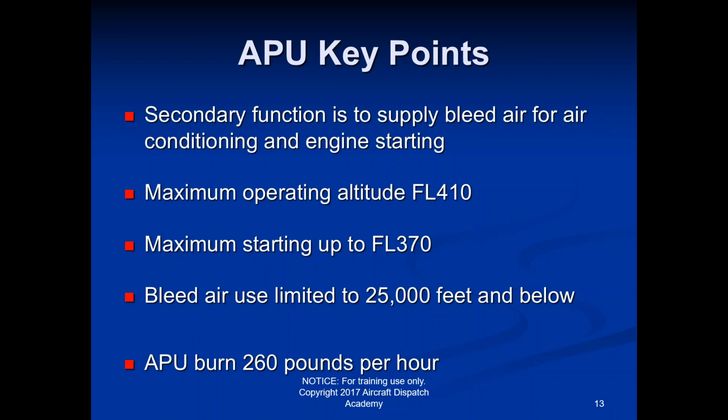That's where he was saying they use it to heat up. In the 700, where it comes out is too high off the ground to really have anybody affected. They moved it up because a lot of people would get burned. If you were standing right next to that exhaust when it turned on, if you didn't know it was turning on and somebody was standing right there, they could get very badly burned. So in order to avoid all of that risk, they ended up moving the APU exhaust high up onto the tail to where nobody can be affected by it. But you also can't warm up your hands.